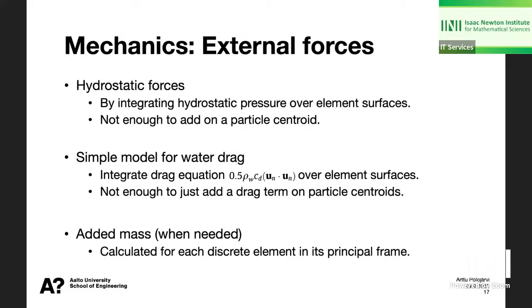These are fairly straightforward to calculate, but it's important to understand that if you want to use any kind of hydrostatic forces or water drag, you often need to use some sort of surface integrals, and they take a little bit of time. You cannot just add them on particle centroids, because there are going to be torques and so on related to those.